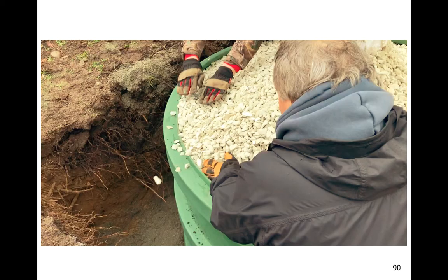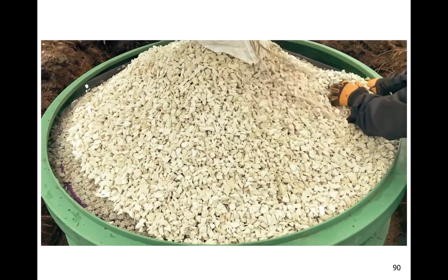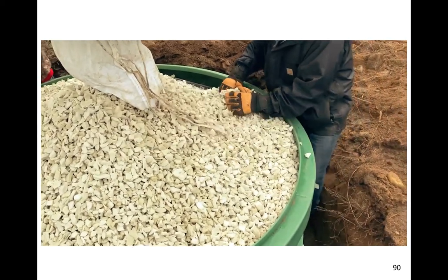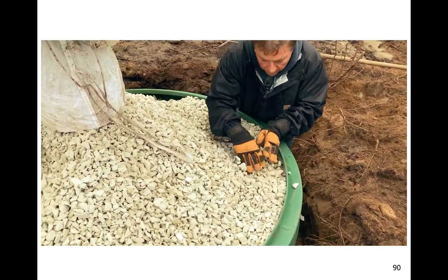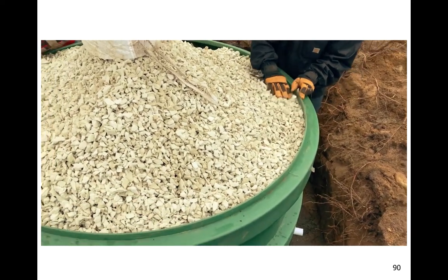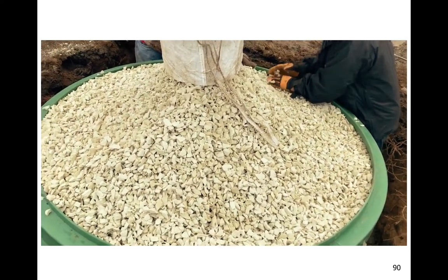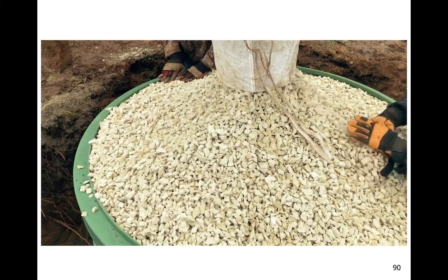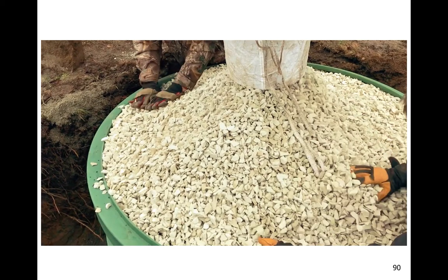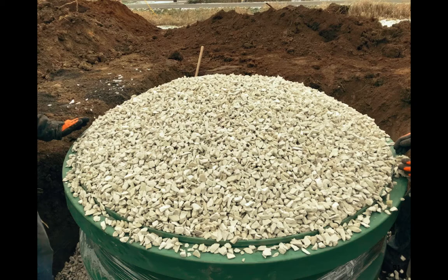So once the mesh is installed, we'll put a little bit more aggregate over the top, and it will be important that you hand pack the aggregates into the upper rib here to compact that mesh down. And this aggregate will settle in. We've got these square ribs, and over the next week or two or three, this media will settle a little bit. So we want to make sure that we mound up extra media on top so that it's there on site in case, it'll always stay covered. And so when we're done, the unit looks basically like this.